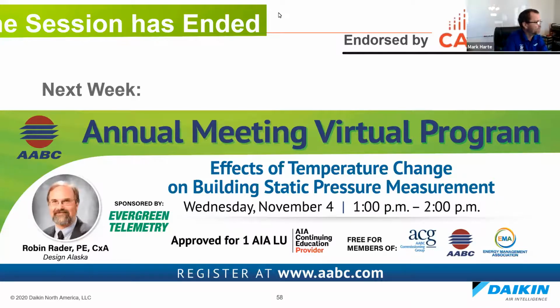Absolutely. With COVID-19 concerns, ASHRAE is recommending minimum of MERV 13 filtration. Can Daikin provide this for all of their indoor unit product line? Some, but not all, I think. I know the cassettes you can, ducted, of course you can, but I don't know about some of the, like the wall mounts and the ceiling hungs. I don't think we have MERV 13 for everything.